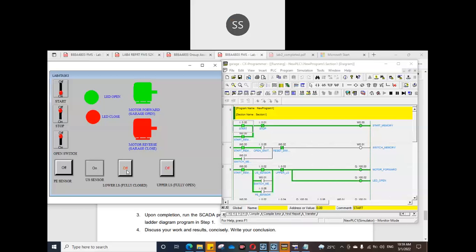Once it's opening, the lower limit switch is deactivated because it is no longer in the closed position. So it's going up. Once it is completely open, the upper limit switch is triggered. Now we can see the motor is stopped. Now imagine the car is entering. When the car is entering, the photoelectric sensor will trigger.